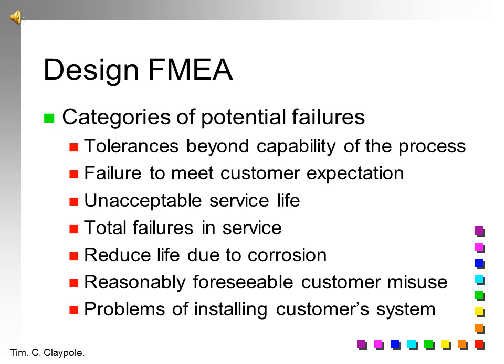If you're designing instruments that go around a process plant and you're having those installed, then you have to design them in such a way that if somebody decides they need to use them as a footrest to get up to reach something higher up, then it won't have any undesirable effect on the instruments inside them. If you look on computer systems, you will see ruggedized industrial units. That's precisely why they're ruggedized. The other possibility with the design FMEA is if the thing you design won't fit in with the customer's system.